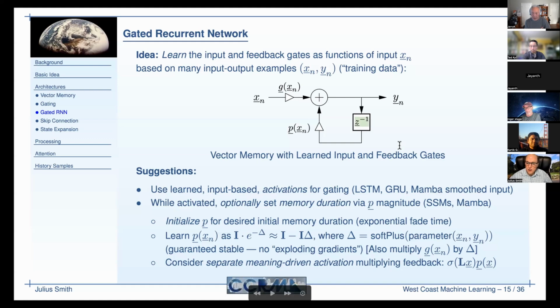And a good thing to say right now is that Z is not an option here. Z is not valid because Z means you have a Z transform, and to have a Z transform, you need a linear time invariant system. Every one of these coefficients depends on the input, right? That is the very definition of a nonlinear system, when your coefficients depend in any way on your input signal. It does not have a Z transform.